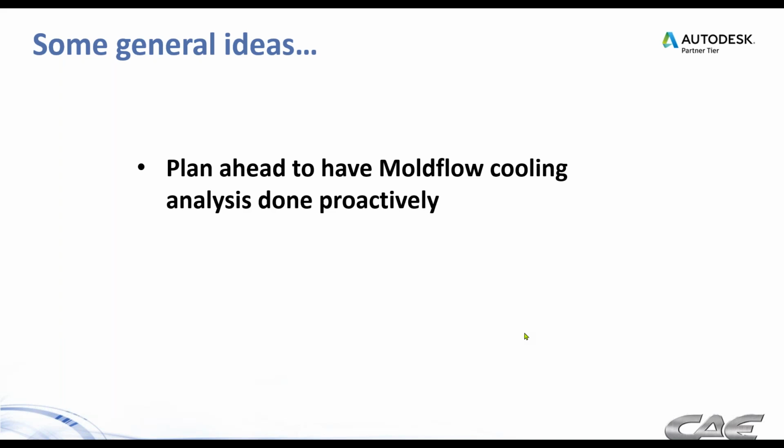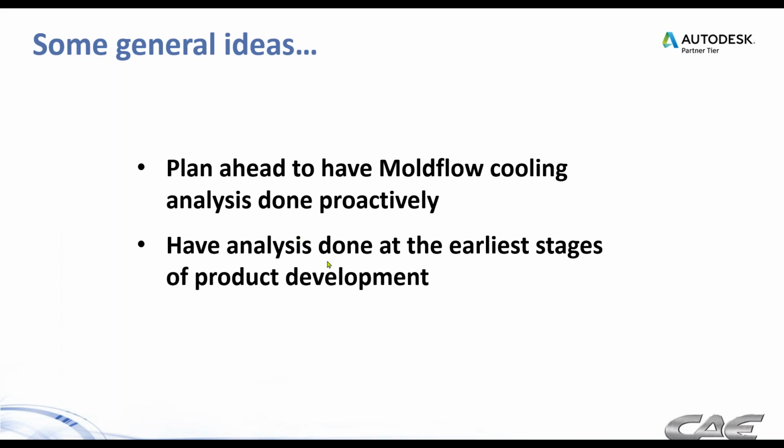So some general ideas, as I preach in every webinar: plan ahead and have mold flow analysis done proactively. It doesn't matter if it's filling, packing, cooling, warpage analysis. Of course, cooling is what we're talking about today, but it's important for anything in injection molding. Have mold flow analysis done way ahead of time so that you have the chance to solve or avoid problems before they become problems at the press. And it's best to do them in the earliest stages of product development.